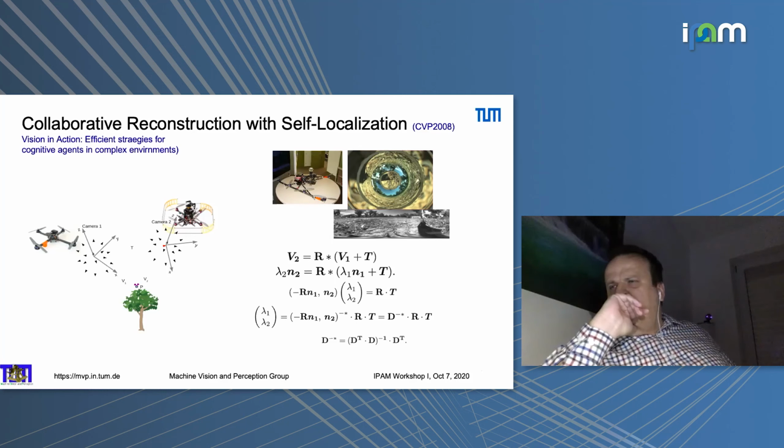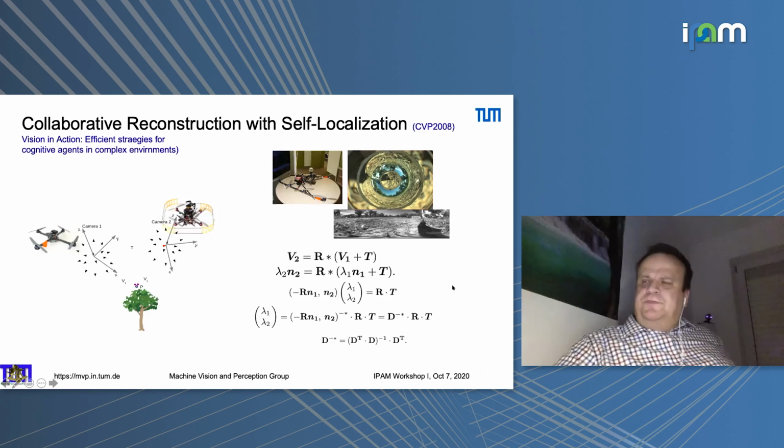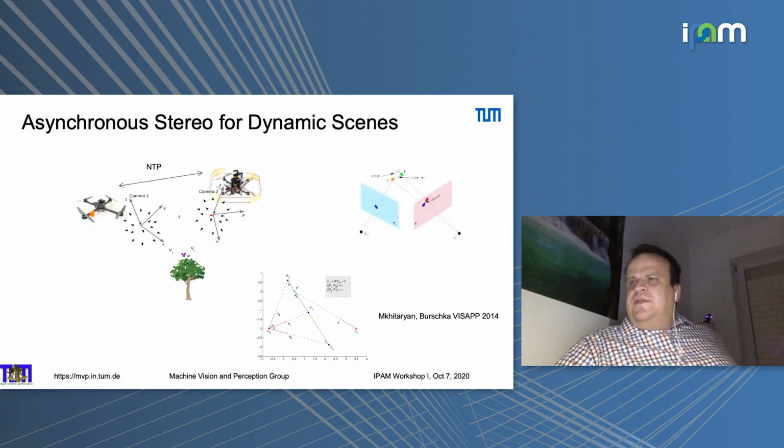Let's just replace the drone with a car. You take 2 snapshots from 2 positions of the camera, and this gives you the 3D structure of the environment in which you're flying. Many people call this a structure from motion approach. What many people forget is this thing will not work if the object you're observing is moving.